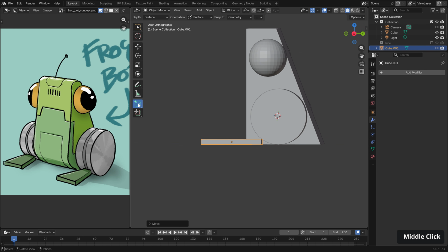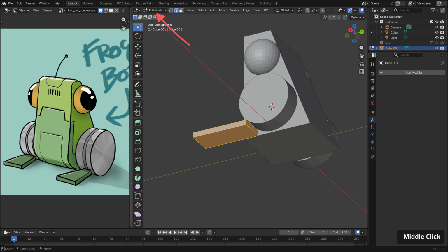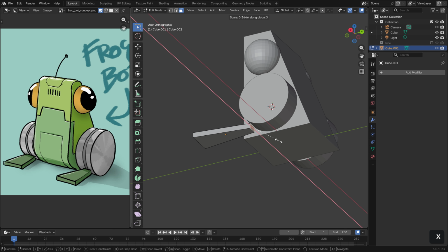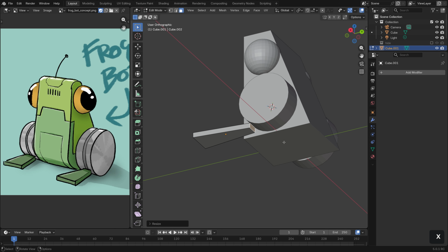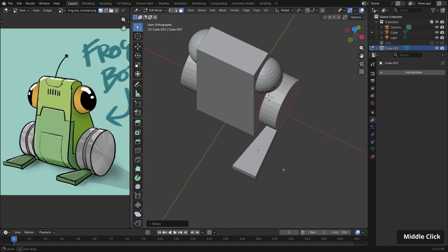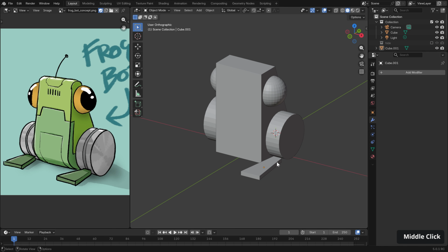So I'm just going to go back to our border select, jump into edit mode, 3 on the number row or up here in the menu, and select the poly and scale with S on the keyboard and X to restrict it to the X axis. Okay, we have our objects all set up. So let's also copy the mirror over to our foot.